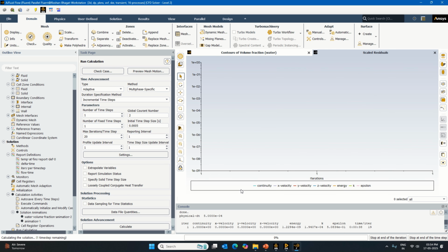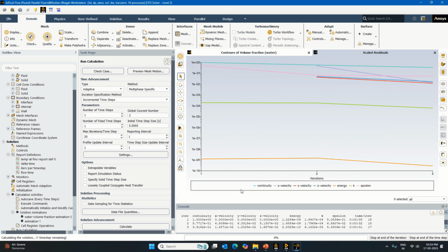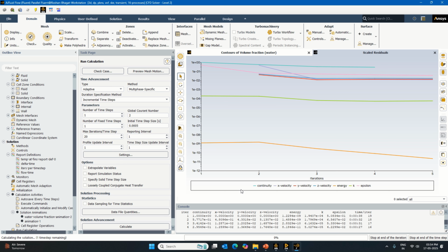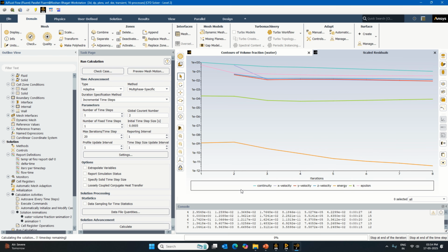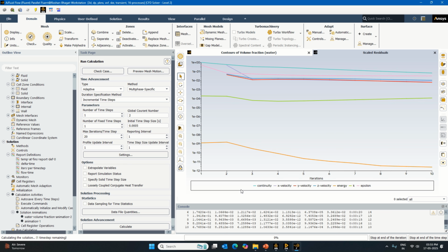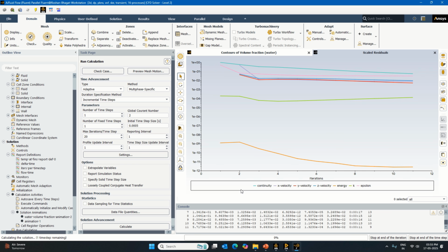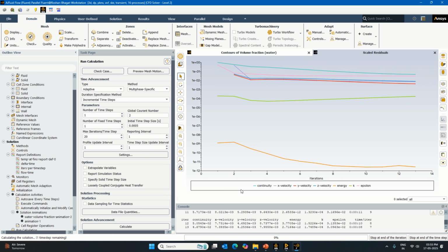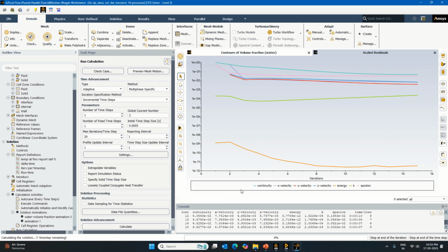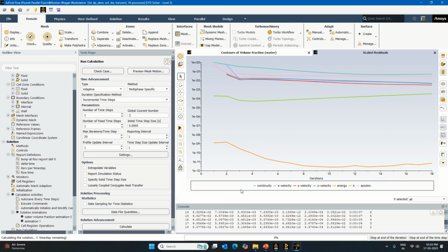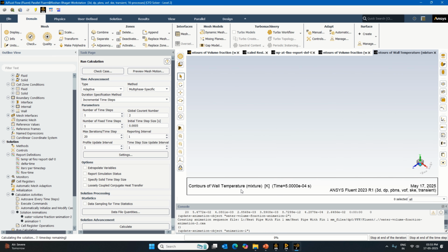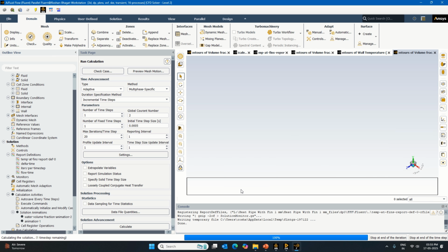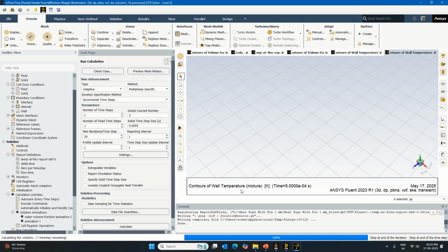So again, definitely this is a task which requires huge time. I will not say this simulation will be completed in the next 1 or 2 hours. Probably it may take some days, maybe 2 days, 3 days, to generate the kind of pulsating flow, because it may need the time step size to be comparatively on the smaller side, just like we have taken 0.0005.